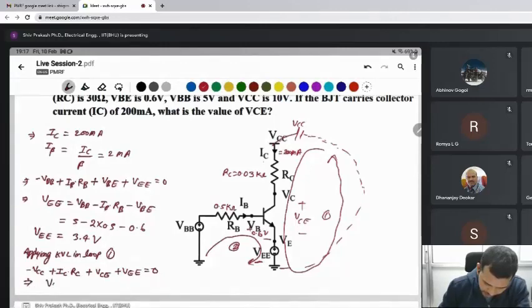Sorry, we require the VCE voltage. VCE is equal to VCC minus IC into RC minus VE. You know all the values.